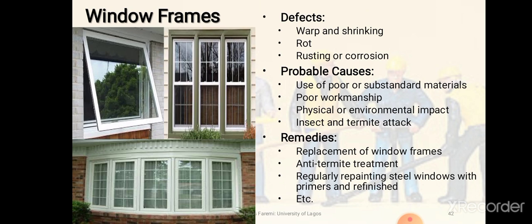For steel window frames that are corroding, regular repainting of such steel window frames with anti-corrosion paints or anti-rust paints or primer will go a long way in prolonging the service life of the steel window frame.